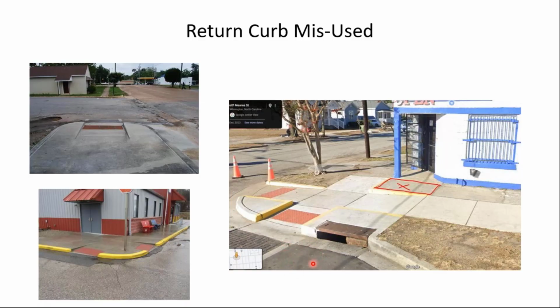This city resurfaced this street that we see a little bit of at the bottom, I guess last summer, and they recognized that when you resurface a street, you need to bring the curb ramps into compliance. So they did that, put perpendicular ramps here. Actually, I guess, a combination ramp to access the store and to access this sidewalk. But the person who sent me this email, who had been to some of my training, said that earlier this year, the store manager contacted him and sent him some surveillance video of people leaving the store. Notice there's a column right outside the door. Apparently they're not